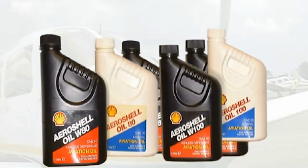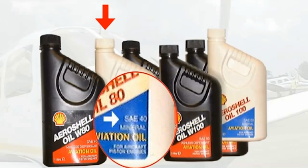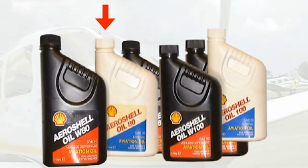If an oil contains no additives, then it is called a straight oil. A straight oil can be recognized by the fact that it only has an identification number. For instance, the bottle marked Oil 80 contains a straight oil. Note that the oil has a viscosity rating of SAE 40. Generally speaking, a straight oil is only used when running in new engines.